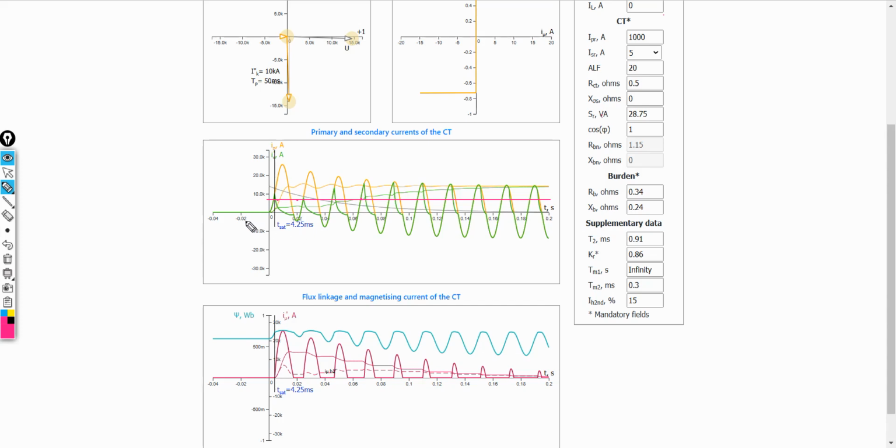It means that for the evaluation of the instantaneous overcurrent protection, it is non-relevant whether the lowest saturation time was calculated or the maximum DC offset is present. The worst case for the instantaneous overcurrent protection is, as just shown, the minimum possible increase of the value in the Fourier filter. In this case, we get the greatest delay.